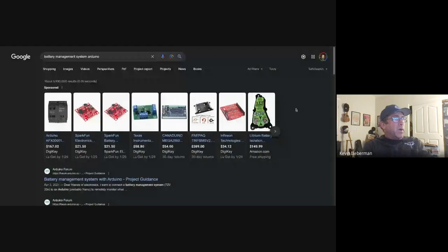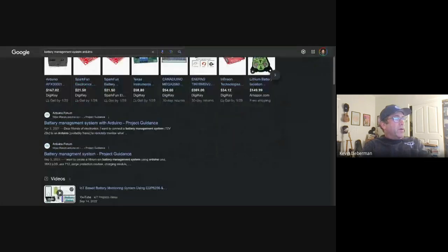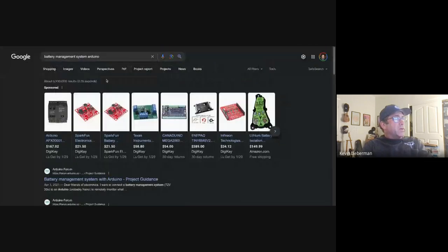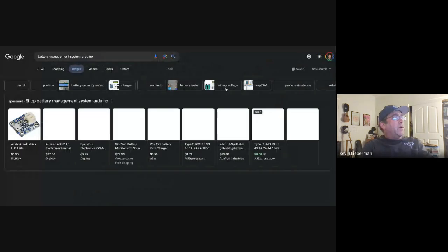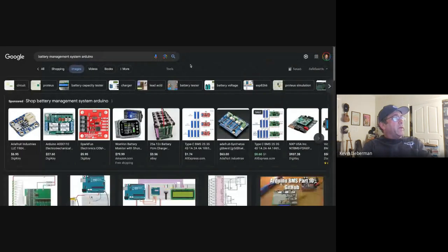So having all of this information CAN bus based helps a lot in collecting all the data and getting all this working with the rest of your car. So your charger needs to know what the voltages are so it knows when to stop charging. Your motor controller needs to know what it is so it can pull back power if your batteries are getting over discharged and warn you if it's getting too low. Things like that.